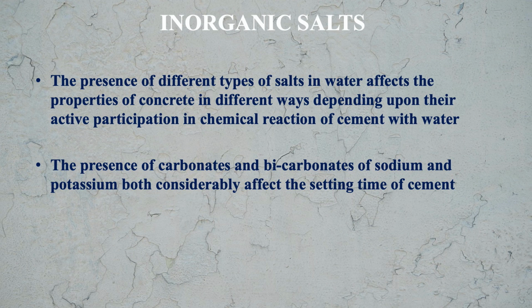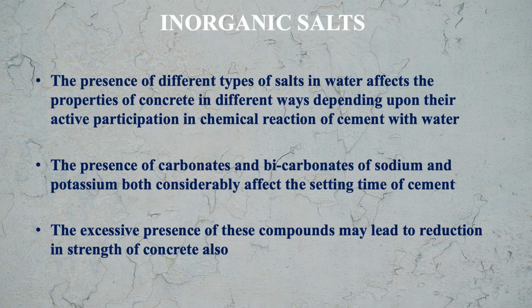The presence of carbonates and bicarbonates of sodium and potassium both considerably affect the setting time of cement. The excessive presence of these compounds may lead to reduction in strength of concrete also. So these are the effects of inorganic salts.